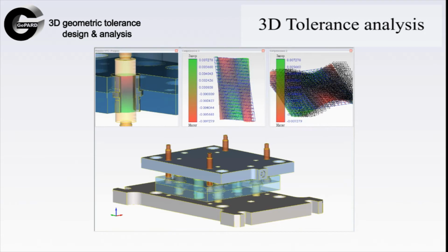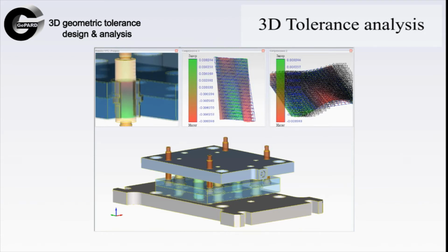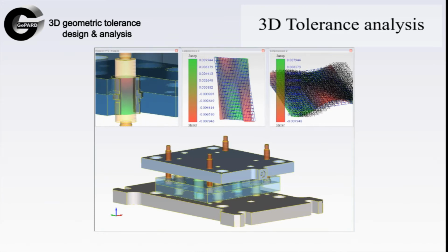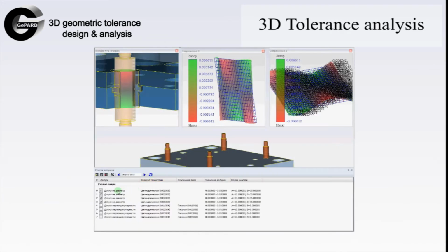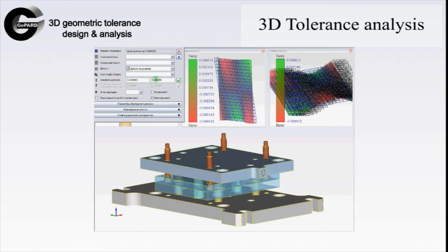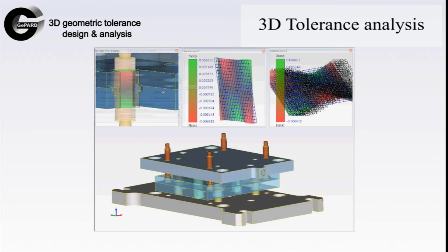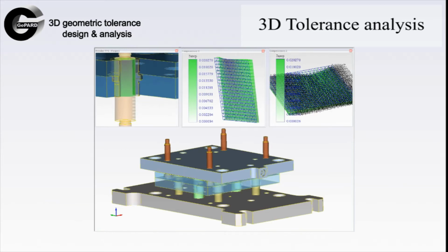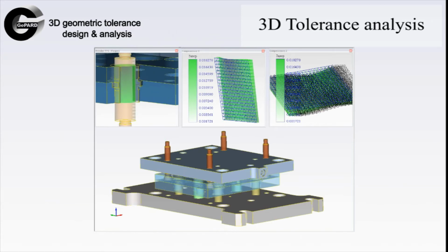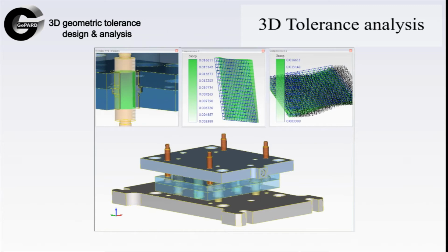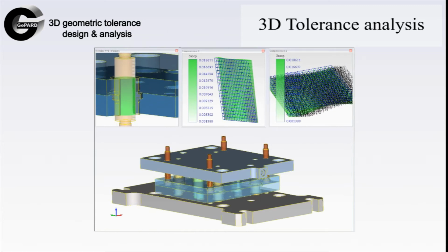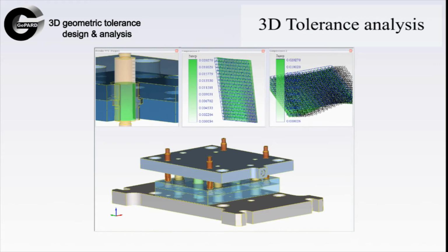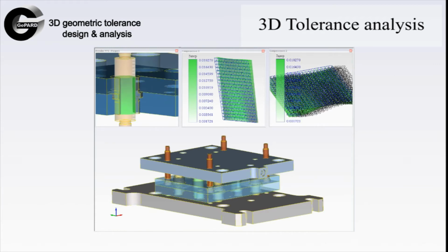Once the tolerance analysis is launched, the system generates a clearance and interference values table. Also, an accuracy graph plots the results from the analysis. With this information in hand, a designer can judge whether the selected tolerance scheme satisfies assembly functional requirements. Assembly is successful if the accuracy graph is green completely. Otherwise, a designer should change the selected tolerance scheme or reallocate tolerances.